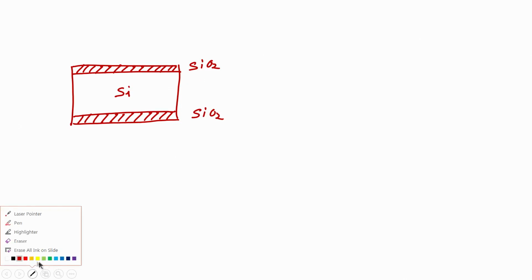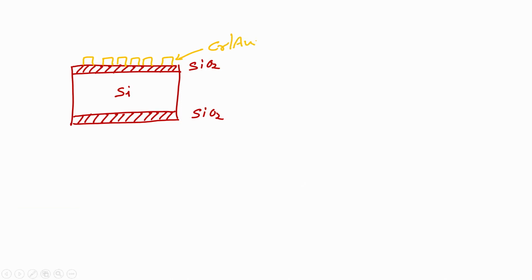On oxidized silicon wafer we have chrome gold, on chrome gold we have P dot PSS, right. This much we have. Now, we have to etch the silicon wafer from back side, from the back side. So, what we will do for that?